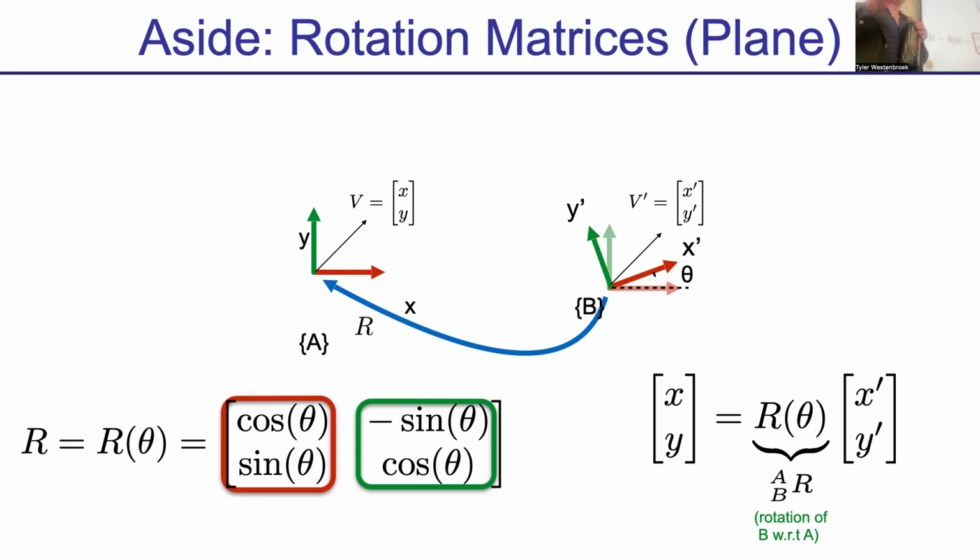Yeah, so that's what we want. The inverse is absolutely a valid way to do it. Do we have another thought on how we could do it? Use the rotation matrix with negative theta instead. Yeah, exactly. Just to put those two together, if I want to go from B to A, that is the inverse transformation of going from A to B, so we can just use the inverse matrix to do that. Alternatively, a way I can get that inverse matrix is, I moved theta degrees to go from A to B, and so to go the other way, I just plug in negative theta, and now I have my inverse.